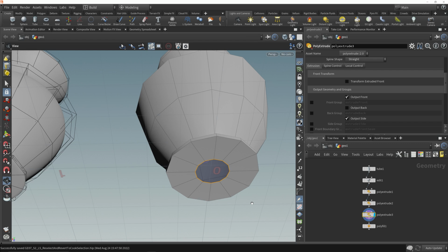Of course, what's different about Houdini is that as we work in the viewport, we're building this network of nodes at the same time, and this allows us to be able to step back through these operations like an undo history. In Houdini, this automatically generated selection is what's known as the cook selection, and there are a few useful things to know about working with cook selections. One is that we can always easily and quickly revert back to the cook selection using the Shift+R hotkey.